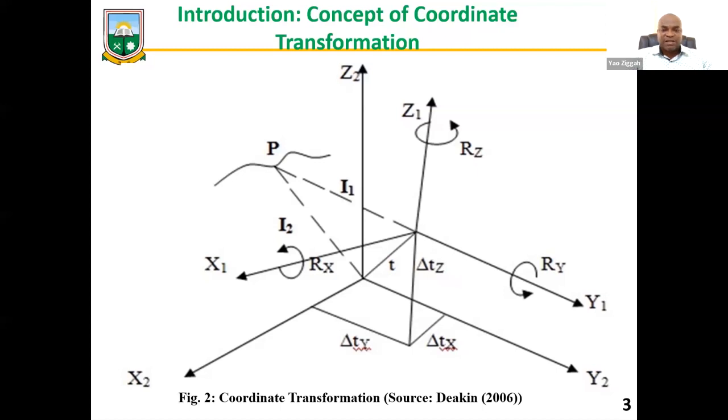Now, when you come back to Ghana, what is our reference mapping system? That is the War Office 1926 ellipsoid. So when you look at the WGS84, which is a global datum, and you look at our War Office, which is a localized reference ellipsoid, it tells you that these two systems are not even the same. And they are not the same in what aspect? You must see that, okay, in terms of their positions, their central point, the origin, are they coinciding?